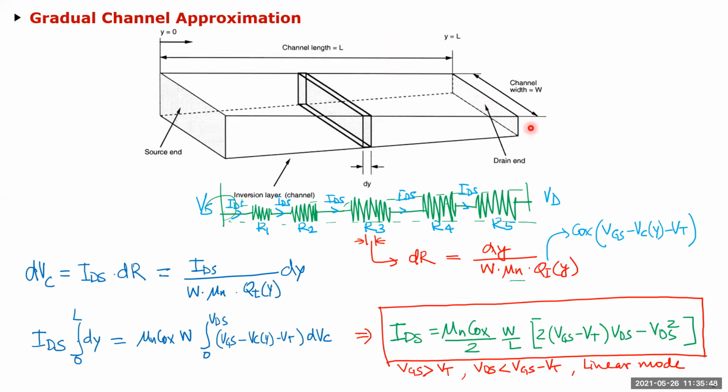Okay, as current is not flowing in the gate, how is the voltage of the gate terminal decreasing continuously? Yes, Sandhyanani, that was a mistake in what I was drawing. The gate voltage is not changing from gate to drain source. You're right, because there is no current flowing, the gate side of it is constant. The drain source side, the channel side, is where your voltage is varying.